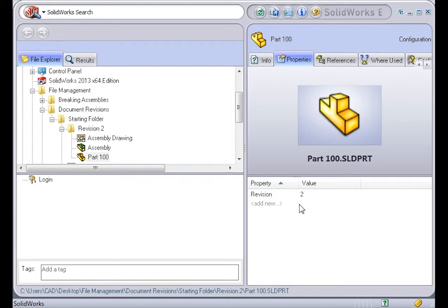To conclude this lesson, let me repeat that this is only one example of how to manage revisions. Some of the nice elements of this method are that the file names are preserved, files that are not modified are not unnecessarily duplicated, and you're left with the history of your revisions that you can always go back to. Give these items some consideration if you decide to create your own file management procedures. You'll be glad you did when you implement PDM software in the near future.